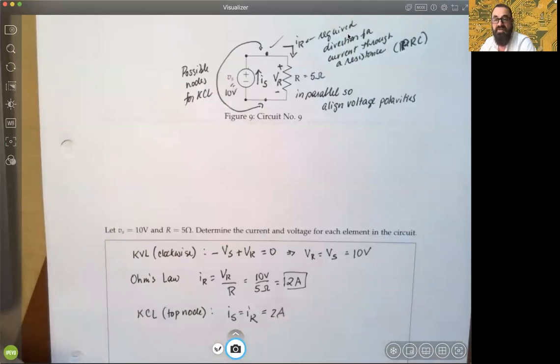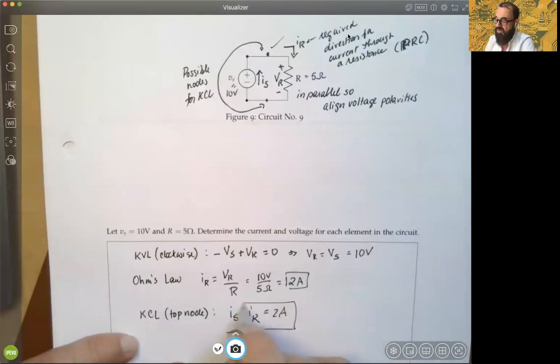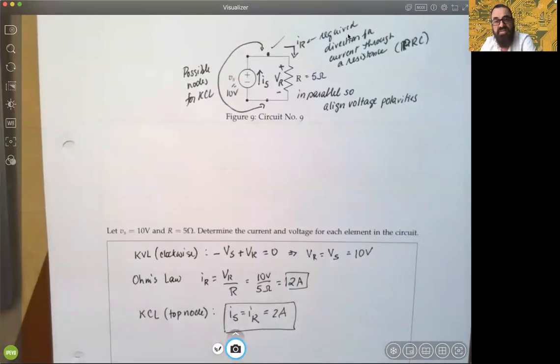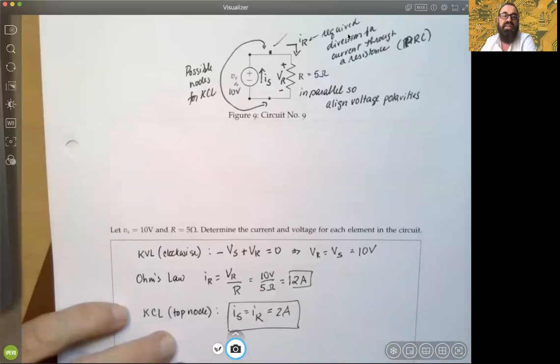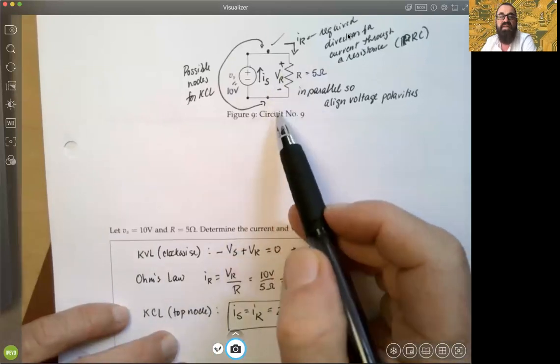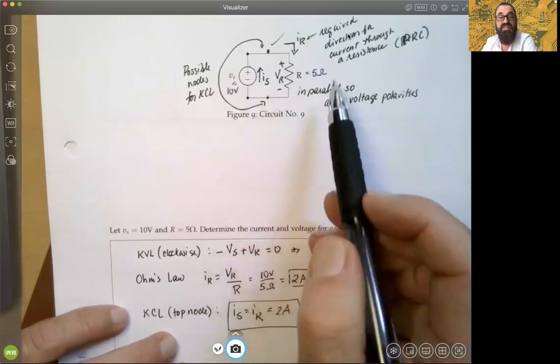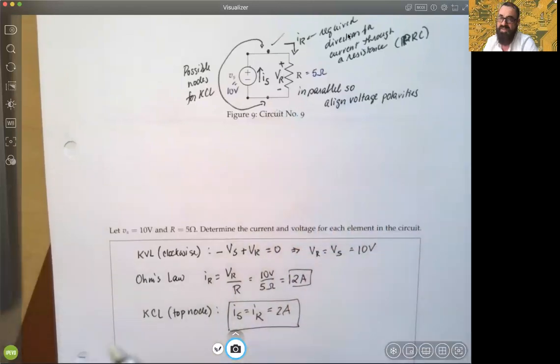Another interesting thing that has happened is notice that the voltages were the same, but the currents were the same as well, because this very simple example loop illustrates that yes, they're connected end to end, but they're also in series. So here's one very simple example, doesn't typically happen, where because you only have 2 elements, they're both in series and in parallel at the same time.